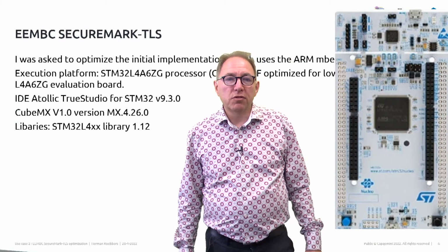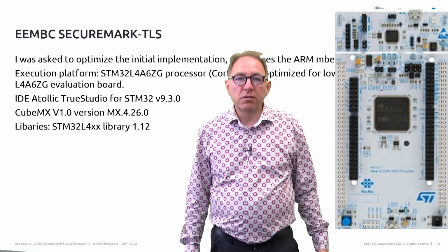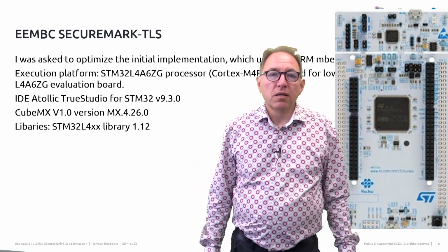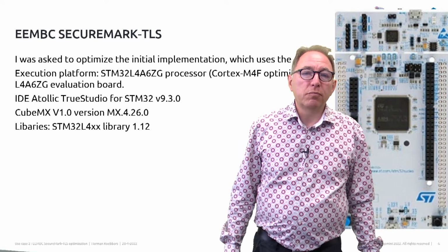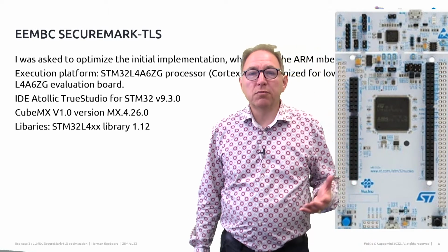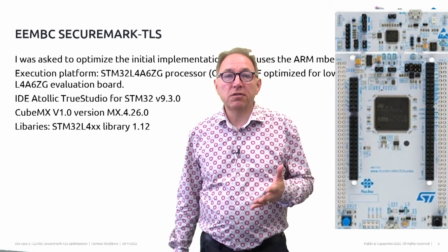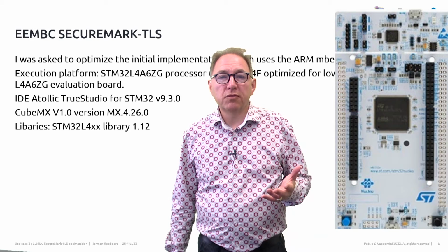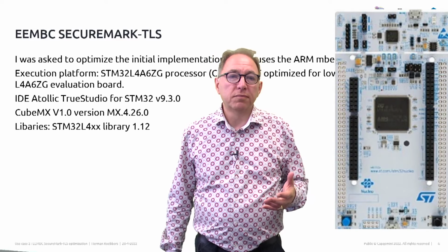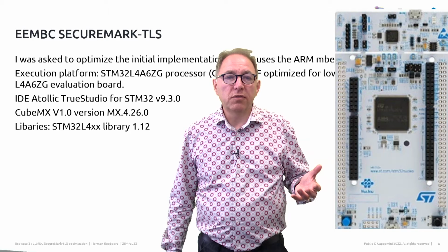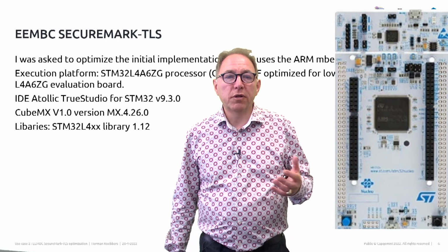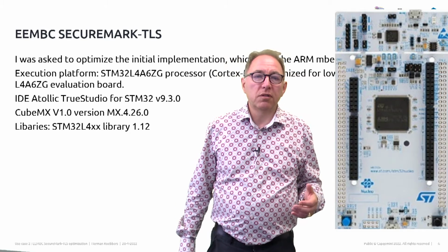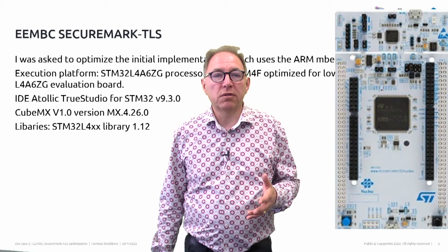So I was asked to optimize this initial implementation using an ARM embedded system on a Nucleo processor board with an STM32L4A6ZG processor, which is an M4F optimized for low power. So we use the IDE, Atollic TrueSTUDIO, CubeMX for the initialization code, and version 1.12 of the specific L4 library.